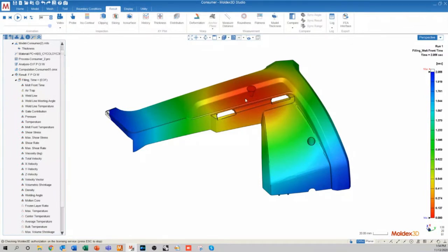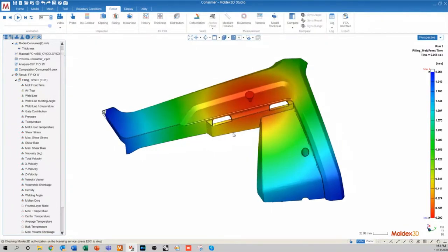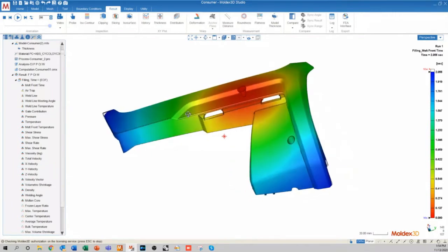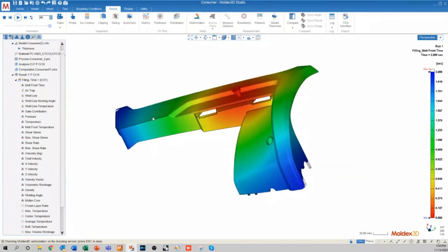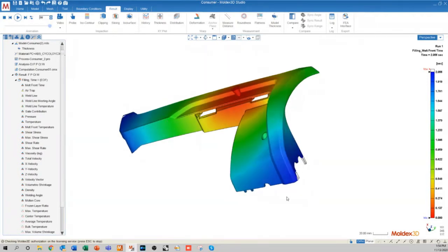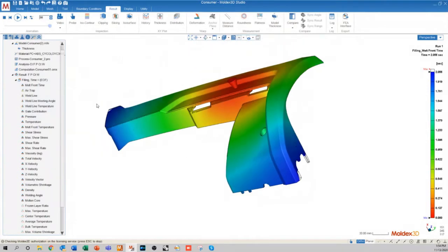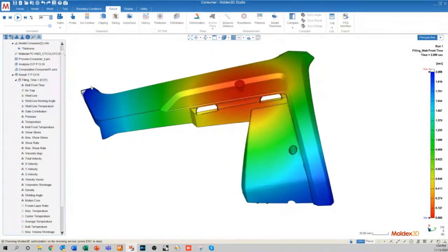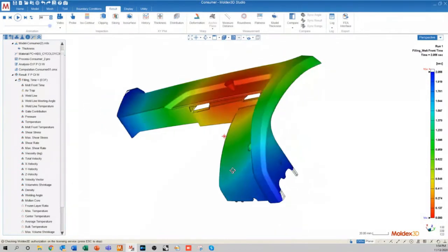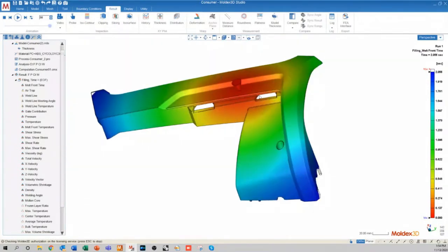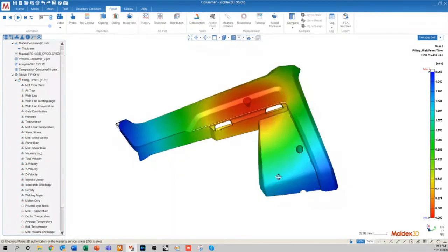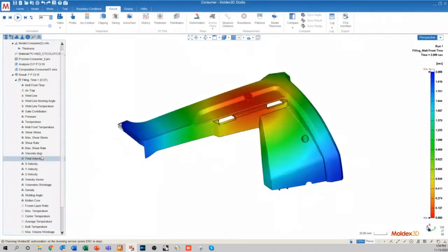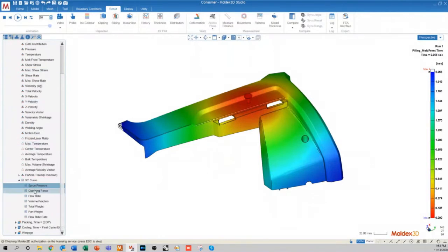The other reason that we look at flow balance is to eliminate any unnecessary spikes. So when I say unnecessary spikes, I'm talking about pressure. So usually if you have an unbalanced filling scenario, if one end of fill region is filled out and the other is not, then you'll actually get a pressure transmission through the gate, and that will cause a pressure spike, which we'll be able to very easily see through a result called the sprue pressure.